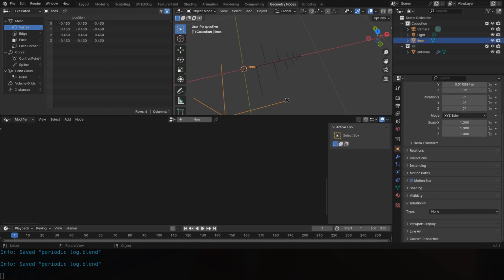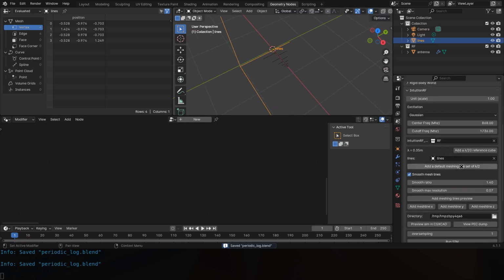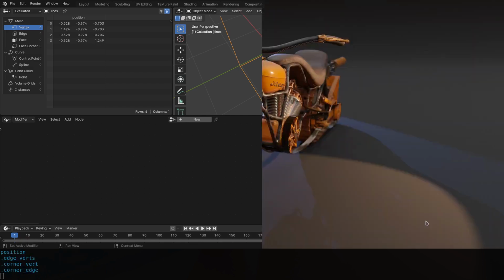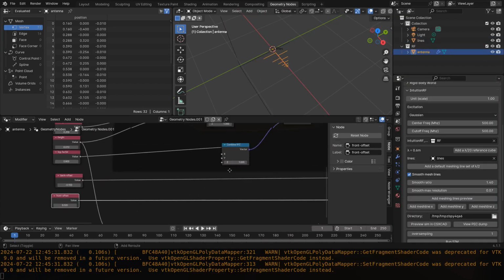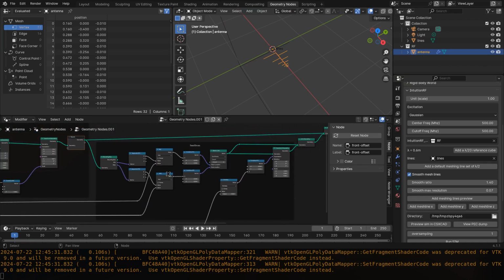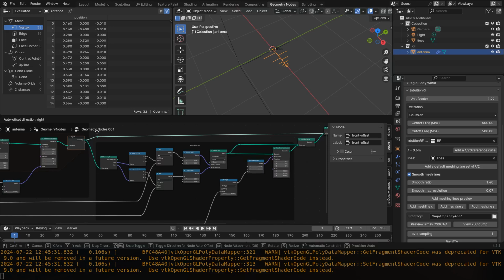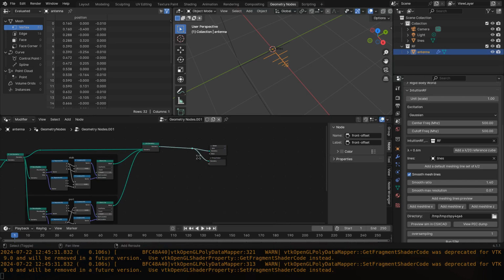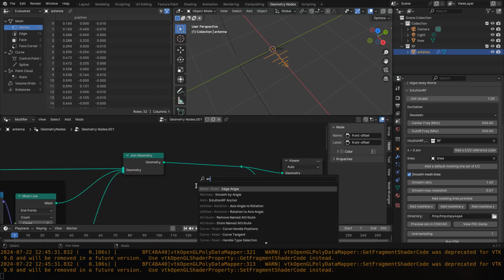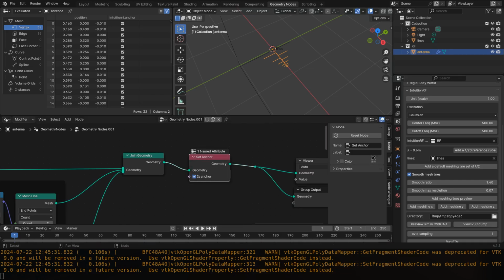Okay, that's the case. Now we can set the domain, scale this up like this. Let's start at this frequency, see what's going on in CSX-CAD. As you can see, there is nothing, and that's because we didn't define any electrical conductor, meshing line, or port here. So let's fix that. I am going to start maybe with the meshing line. So let's define everything as a meshing line like this.